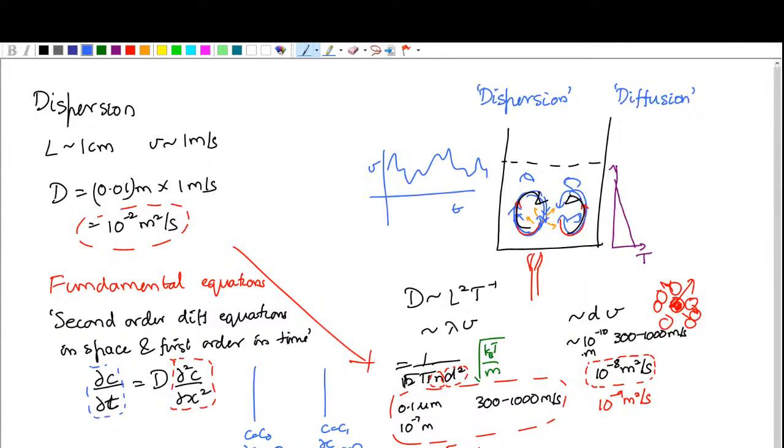Okay? The temperature condition would be either a constant temperature, if that PFR is maintained at a constant temperature, or it could be a constant flux condition if you're giving a constant input of energy at the wall of the PFR. Okay? And the momentum condition is, of course, the no-slip condition, that the velocity at the wall of the pipe is 0.